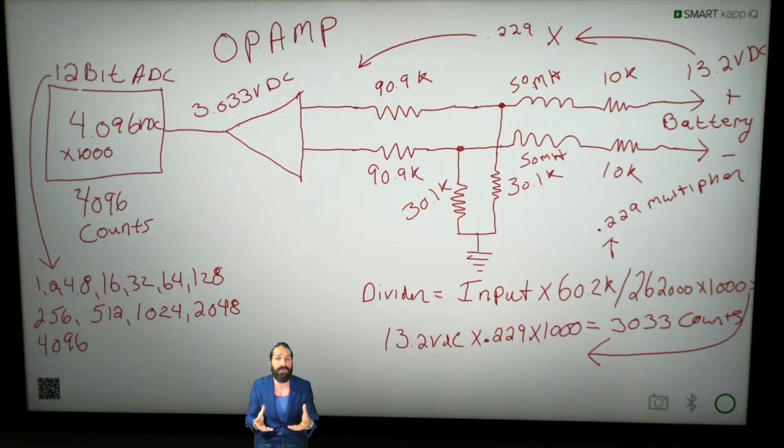So when you're designing new systems and microprocessors, we want to choose a higher quality ADC, like a 16 to 24-bit ADC, so we do not have to scale so much in regards to some of these systems, because it creates quite a bit of troubleshooting headaches down the road when you're troubleshooting something 15 years old and it has this antiquated circuitry and you don't quite understand. This is why divider circuitries are so important, and you have to understand it. So what it's doing is scaling that down.